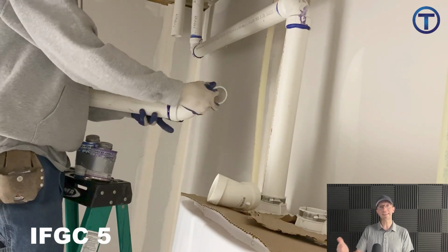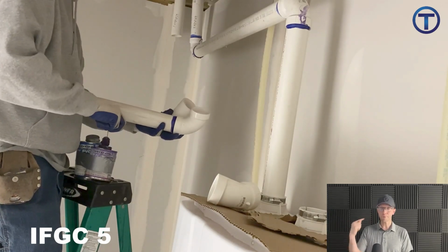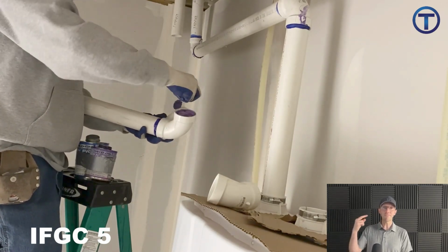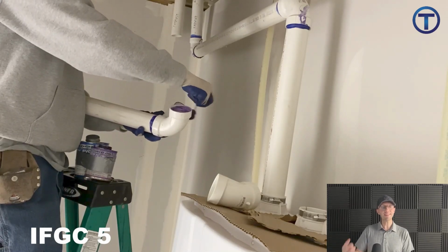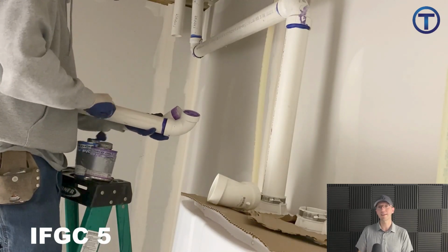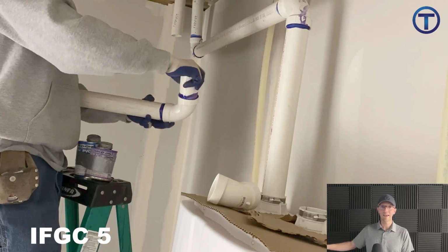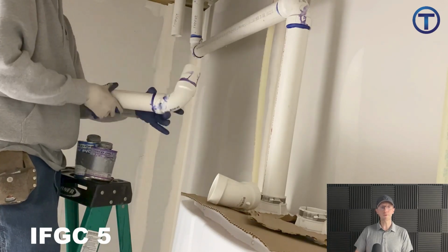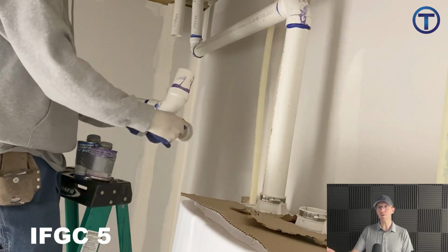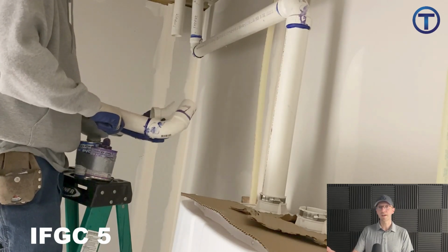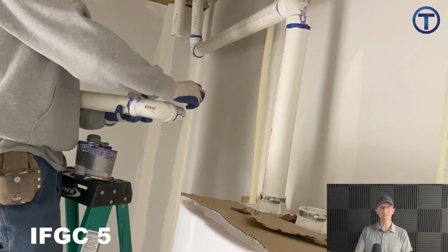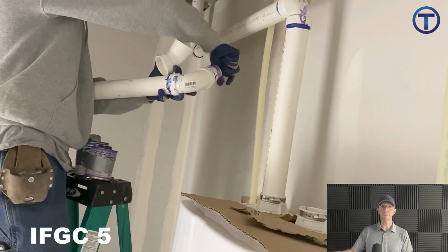And a good joint is going to consist of properly priming the PVC before applying the glue. That's an important part of this chemical process. And if you're doing DWV and you're just installing drains, well, yeah, code has made room for that. Just use glue as long as it meets that standard. You don't have to prime up to 4-inch pipe. But that's not what we're talking about here.